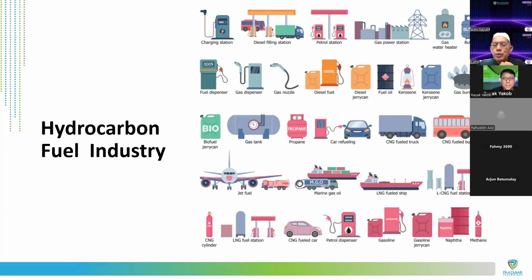FPSO actually should be the trend in the future because FPSO removes the requirement of a platform. But to have an FPSO, you need subsea wells, and subsea wells normally require maintenance. So that's why in shallow water we try to avoid subsea wells, so that we have a platform to handle all the production and we go for the maintenance of the well comfortably with the platform.